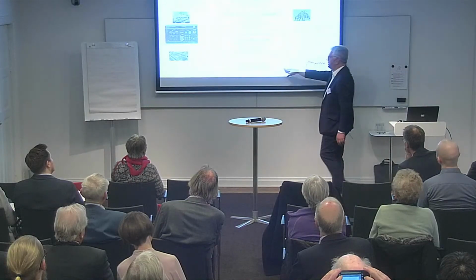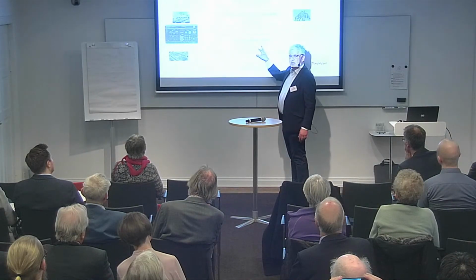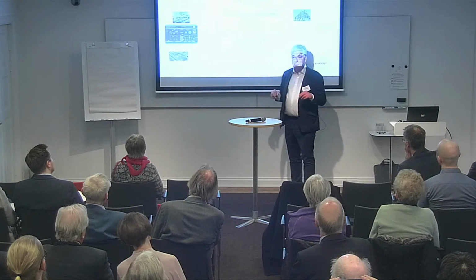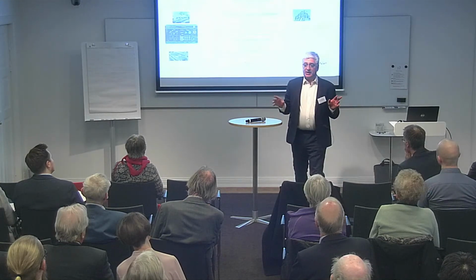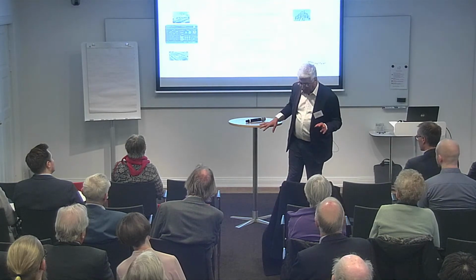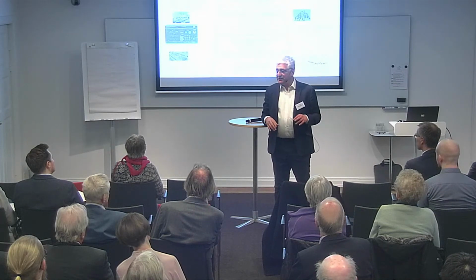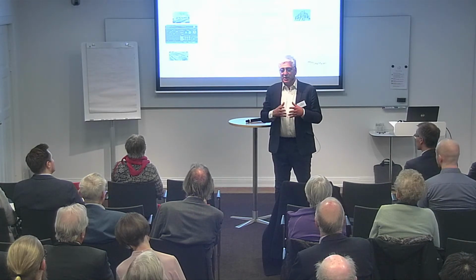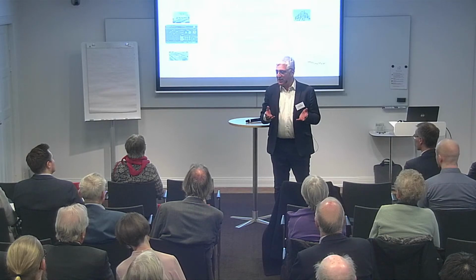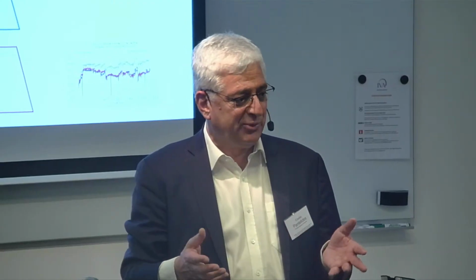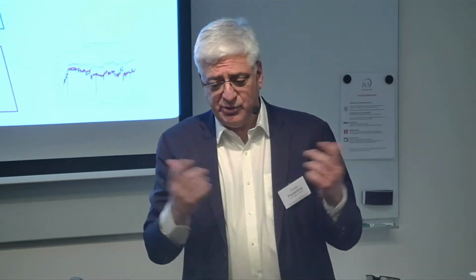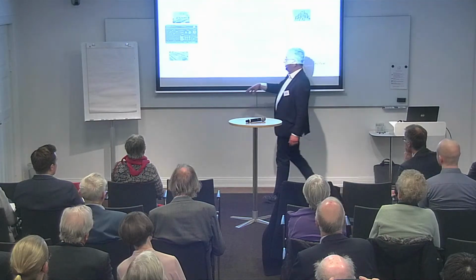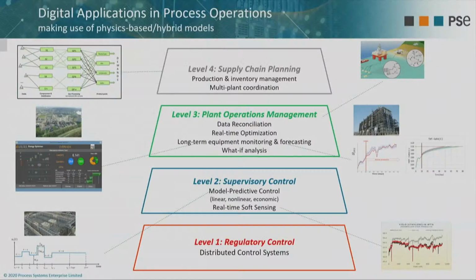For example, if I do model predictive control, it would be linear MPC, and you use a linear model, which doesn't rely on any physical understanding. You just go to the plant, you kick the plant around for weeks on end, and you see how it responds. You make yourself extremely unpopular with the plant operators and the plant manager because you disrupt their plant for weeks or months, okay? And in the end, it doesn't work that well, but that's it. Nowadays, what they're saying is, forget all that. We have all these physics-based models of polymerization reactors, so we can actually use them.